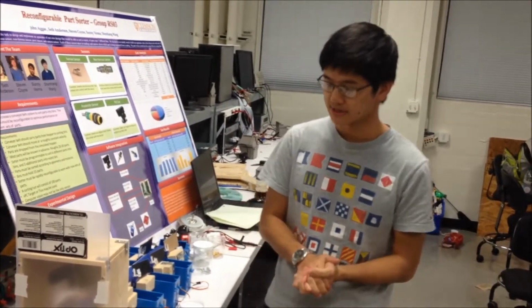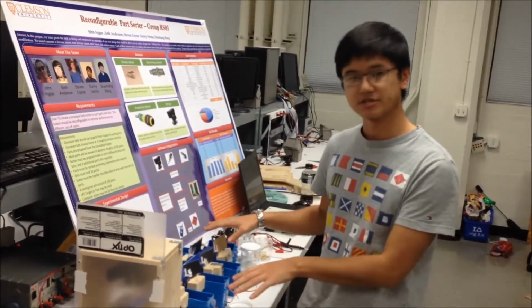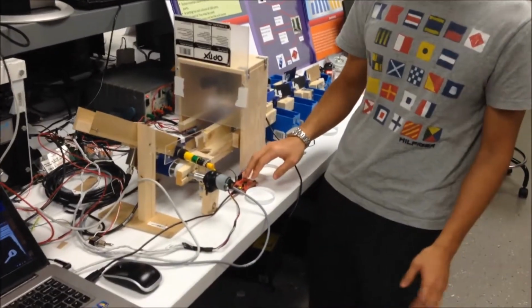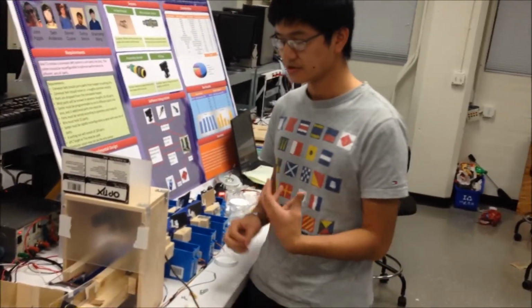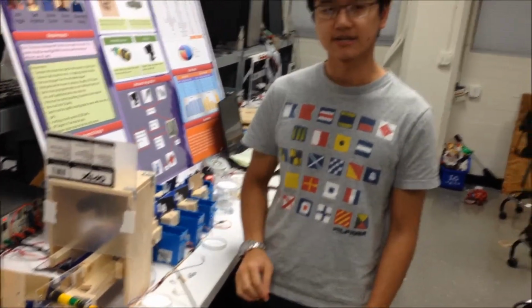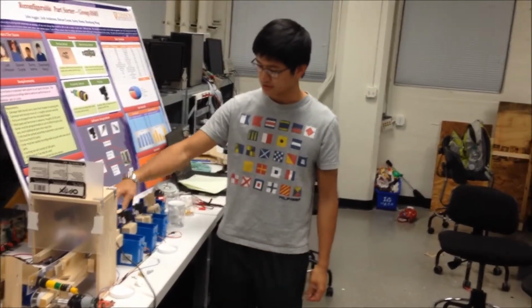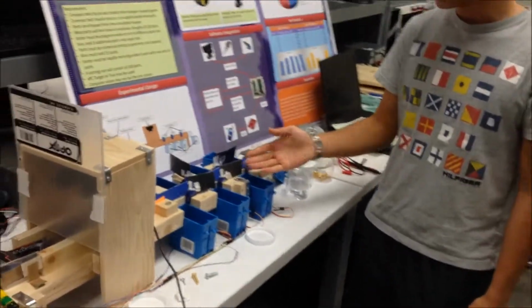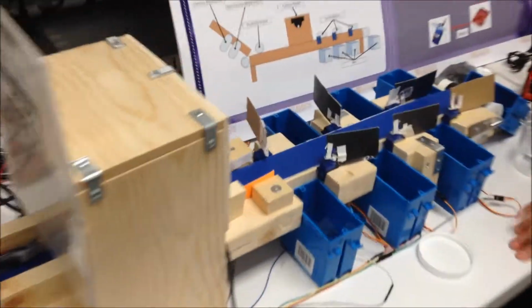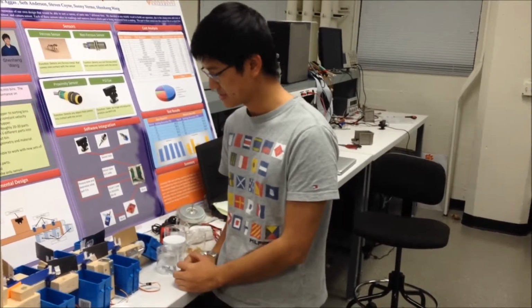And Simulink takes this data, Simulink will give a certain delay to this data depending on the position of the bin, and then it will relay this data to TIVA, another microcontroller, and TIVA is used because it has many, many PWM outputs. And TIVA basically serves as a signal relay for these PWMs, and it will send PWM signals to each of our 6 servo motors, shown here. Every one of these servos corresponds to a bin, and utilizing the PWM output from TIVA given at the right time, it will sort the pieces into the respective bins.